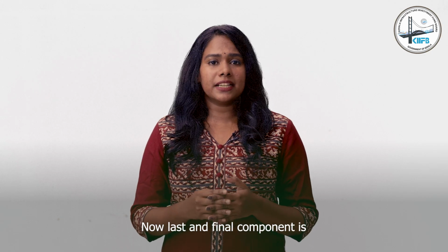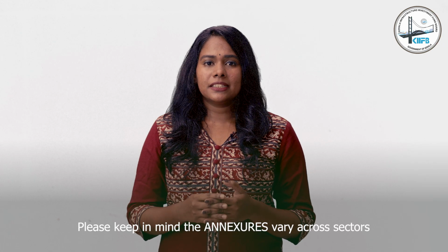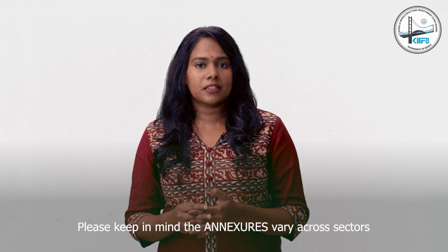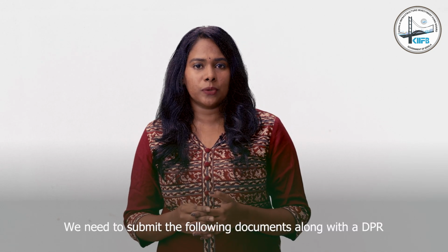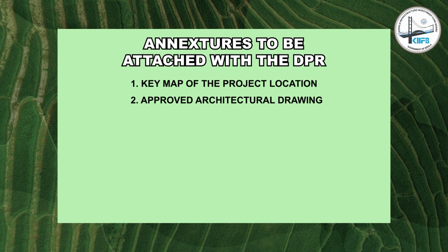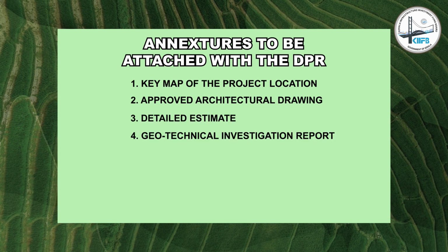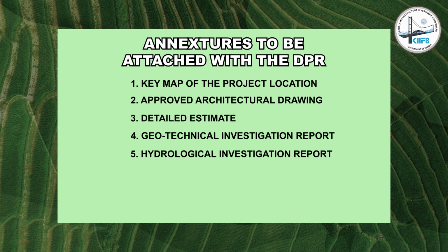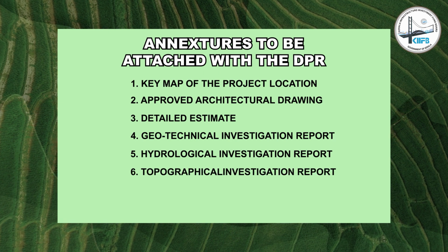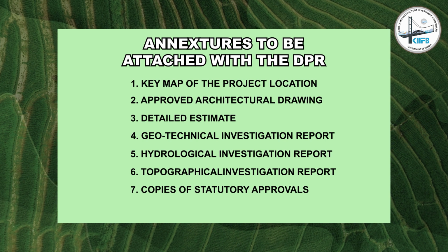Now, last and final component is annexures to be attached with the DPR. Please keep in mind that the annexures vary across sectors. We need to submit the following documents along with the DPR: key map of the project location, approved architectural drawing, detailed estimate, geotechnical investigation report, hydrological investigation report, topographical investigation report, copies of statutory approvals.